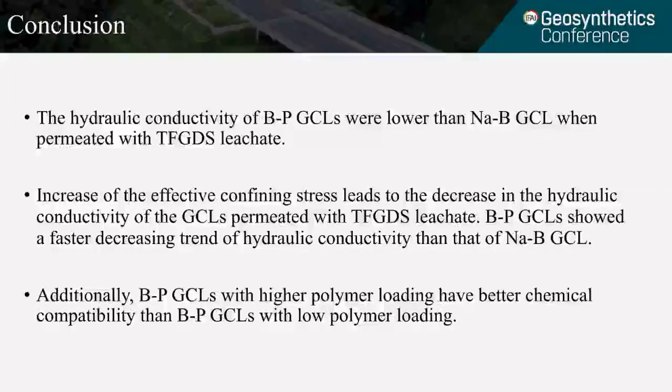And additionally, we do observe that BP-GCL with sufficient polymer loading can maintain the low hydraulic conductivity even at low confining stress conditions, which is a good sign that BP-GCL with sufficient polymer can be used to manage aggressive leachates from CCP disposal facilities.